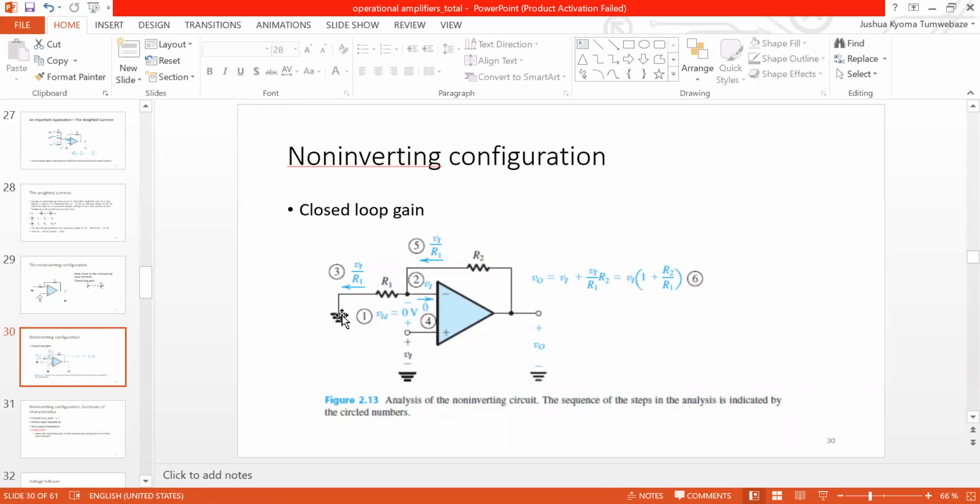Alternatively, I always give students this alternative, that you can choose to set your direction in the opposite way. So you let this current flow from the earth into R1. You'll see that you'll come up with negative values, which will imply that the current flows in the opposite direction. I hope that is clear.